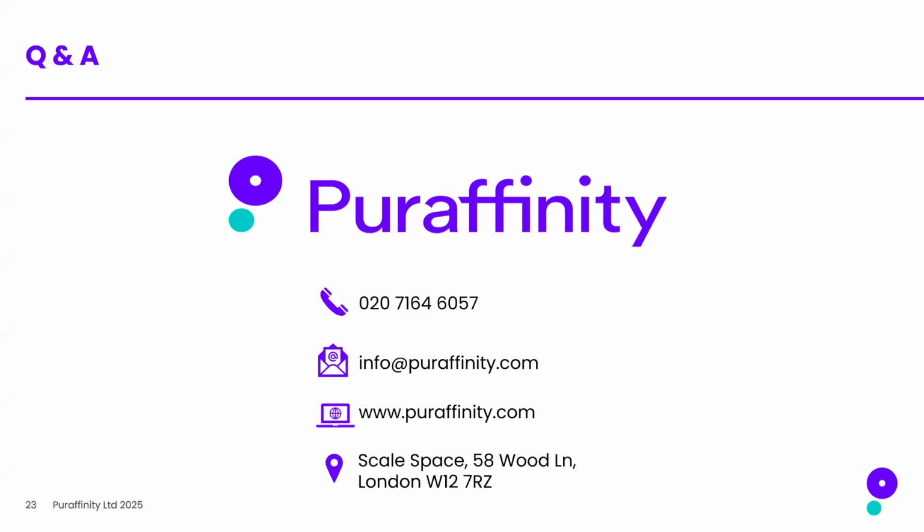What flow rates do you operate at? It's not necessarily a flow rate, it's contact time and linear velocity. So really we could operate it at whatever is out there, but it would fit into our linear velocity and contact time recommendations back on the slide that showed system design. Can the media be regenerated? We are working on that. There's currently a project on regeneration.